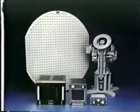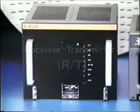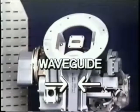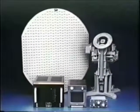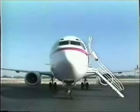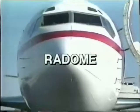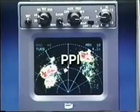The Bendix ARINC 700 series airborne weather radar installations contain 5 basic components: a receiver-transmitter unit for transmitting, receiving, and processing the radar energy; a waveguide which guides the microwave energy back and forth between the antenna and the receiver-transmitter; an antenna which focuses the microwave energy into a beam and continually scans it from side to side, and has the ability to point it at a specific elevation angle; a radome, which is a protective covering for the antenna that allows the pulses of microwave energy to pass through; and a display unit, which displays the processed radar echoes as well as provides a mounting point for the system's controls.